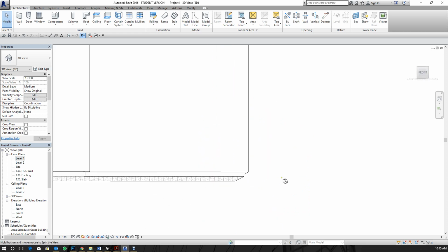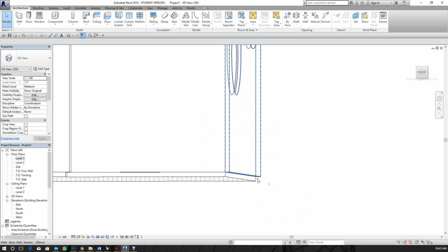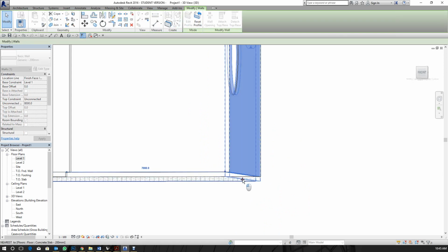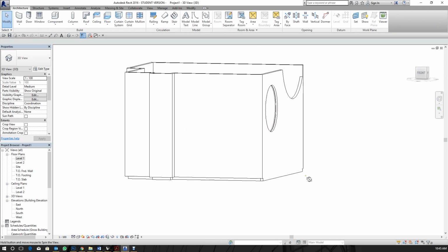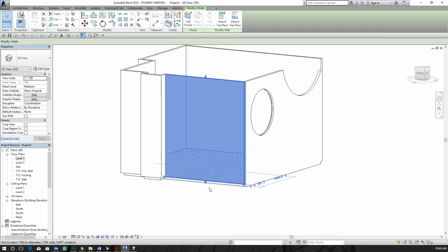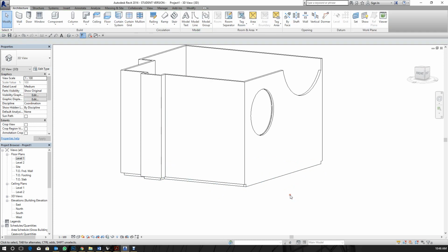And this doesn't look normal, because you wouldn't see that. So I'm just going to drag that wall down so that it snaps. And instead of having to drag all of the other walls down to snap with the level of the floor, I can do a match property.